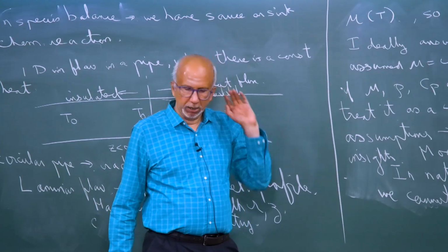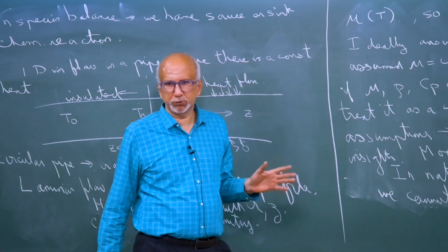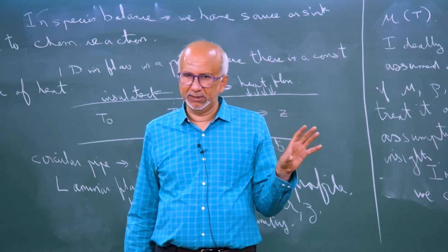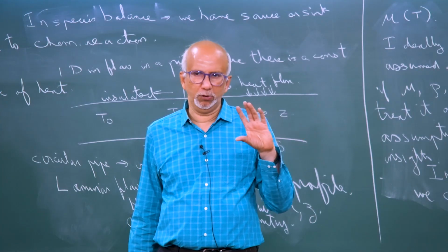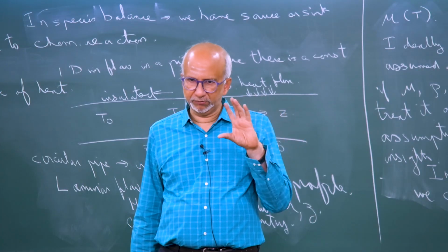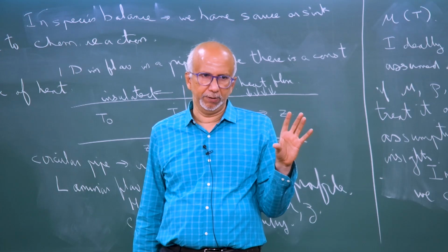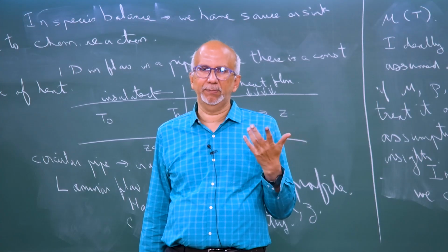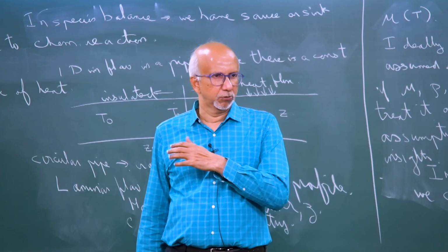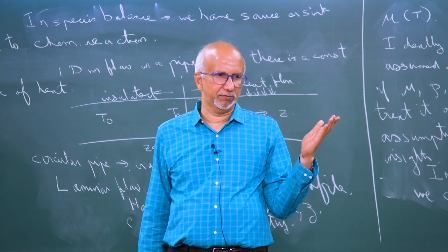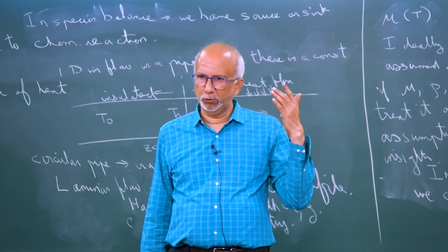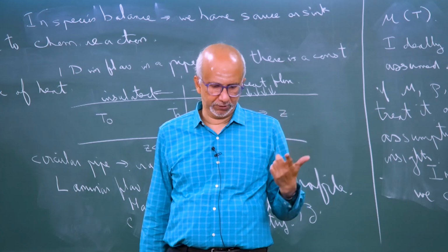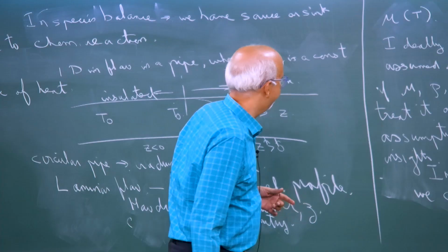So, now we come back to our problem. To cut a long story short, we are not going to worry about the fact that the viscosity is going to be changing with temperature. We are going to assume the laminar profile is valid for our problem. So, then you have this great fluid where viscosity does not depend upon temperature. Then the laminar flow velocity profile is valid, and we are going to use that and proceed with the solution. So, keep that in mind, some assumption is here.